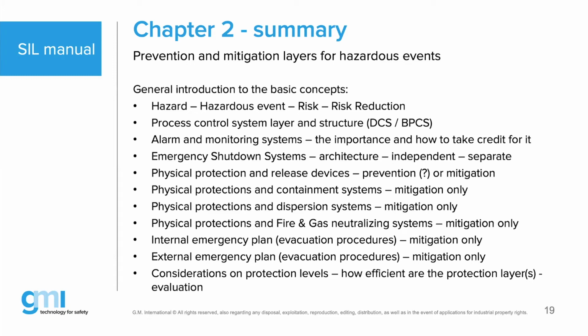Now, when that layer goes wrong, which can often be the case for whatever reason, we need to alert, alarm, or monitor those types of items. The important thing here is how you will take credit for an alarm coming to an operator. That's the first question. And the second thing is, even when the alarm is there or not there, or even when the operator makes a mistake, or didn't hear the alarm, or maybe didn't take the correct action, we need to have a layer that is independent and separate from anything else. And that layer is called the ESD layer.